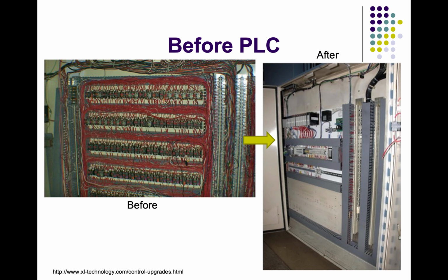Before PLC, we had to wire everything by ourselves, and it was all messy, and customization was not at all possible because these all were relays. We are turning something on and off, and we have to wire them by hand, and they were not programmable. After PLC, it has become nice and tidy, it also saves space, and we can easily customize the program according to future needs.